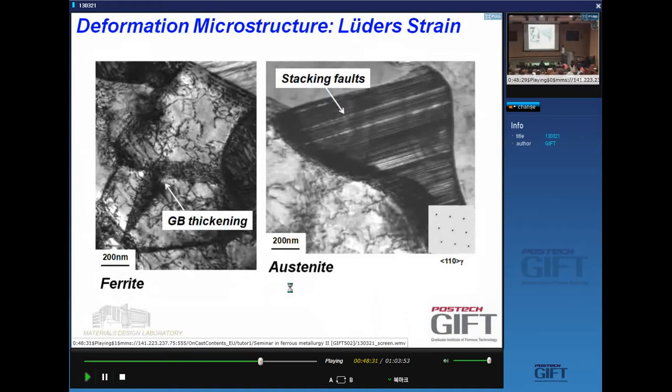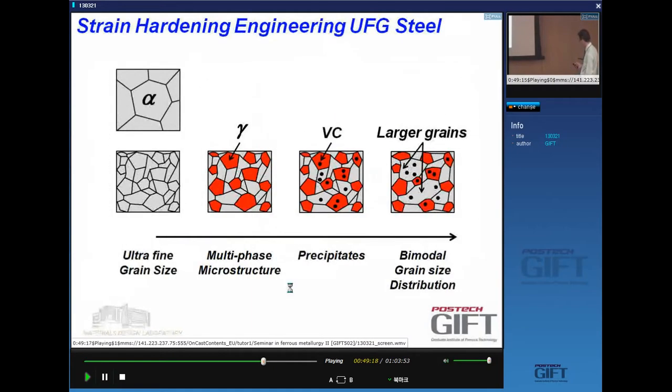In addition to this, we've seen a lot of very interesting deformation patterns. For instance, when the austenite does not transform to martensite, it still does plastically deform, and it does this by the dislocations that do the deformation being partial dislocations. So all these lines here are not twins, are not martensites, they're just stacking faults, and what you basically have are the grain boundaries emitting partials, and that's a sure sign that it's very difficult to nucleate or to have dislocation sources in these ultrafine grained microstructures. So you have this, again, a wonderful material that doesn't do it.